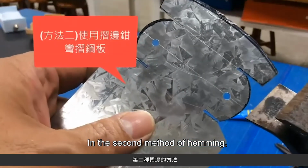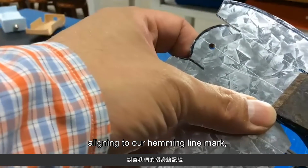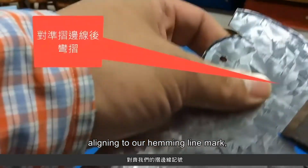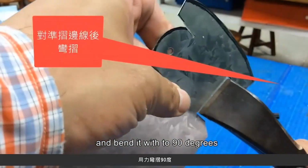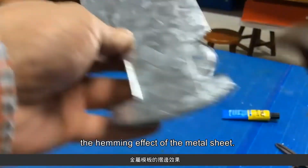In the second method of hemming, we use hemming pliers to clamp our material, aligning to our hemming line mark, and bend it by 90 degrees, which can also achieve the hemming effect of the metal sheet.